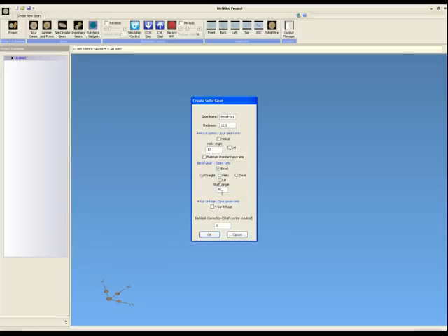90-degree shaft angle. One change comes into effect at this point. The gear thickness at the top of the screen no longer reflects the actual thickness of the gear. It now reflects the face width of the gear. Face width of the gear is the distance of the thickness of the teeth measured from the outside to the inside. This means it has a sinusoidal relationship to the actual thickness of the gear. So by specifying a 12.5 millimeter thickness, I may be specifying as little as 5 millimeters thickness for the gear, depending on the conical angle of the bevel.